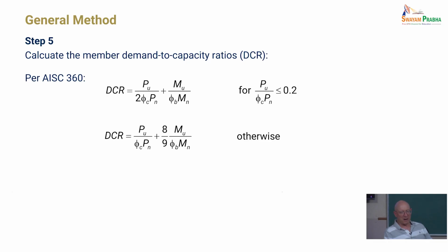quite honestly, the bilinear equation in AISC 360 is a bit of a cheat when it gets to some of these cross sections that have very thin webs. The better interaction equation is really just the linear interaction equation for that, and we're pointing that out in the paper that I was showing you the figure from here at the start of this session. And it's pointed out in the bridge standard that, look, if you've got a slender web, you should use the linear interaction equation.